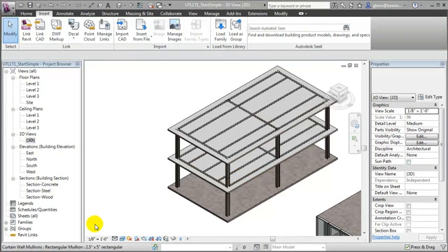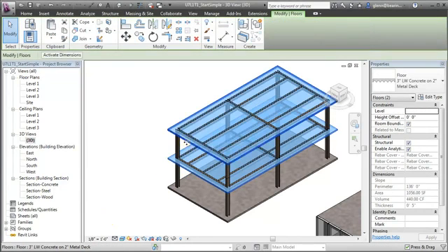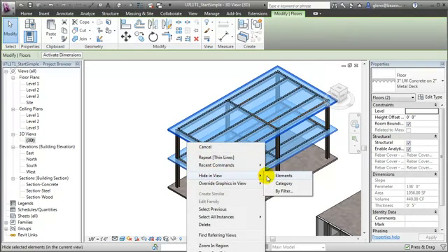The structural floor slabs are located at the correct elevation, but the beams and beam systems are actually protruding up through the floor slabs because they're located too high. Rather than placing beams and beam systems right at the floor level, we should take the thickness of the structural floor into account and lower the elevations of those beams and the beam systems. Let's look at how that's done. Let's hide these floors to make it easier to see the beams and beam systems. We'll select one floor, then Control-click to select the other, then right-click to hide them.